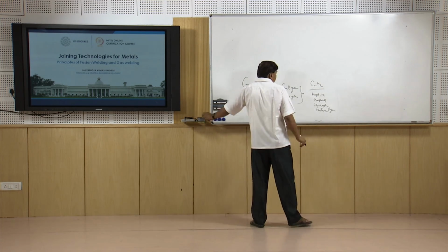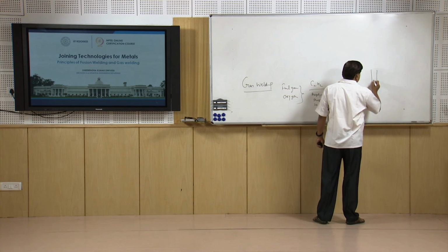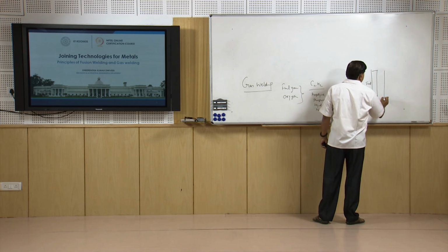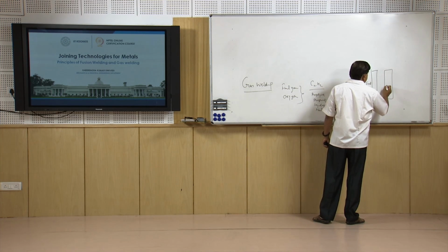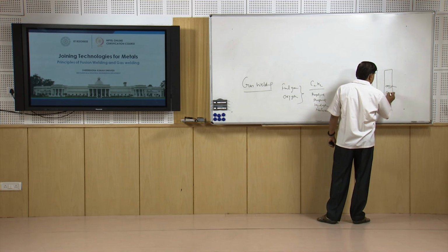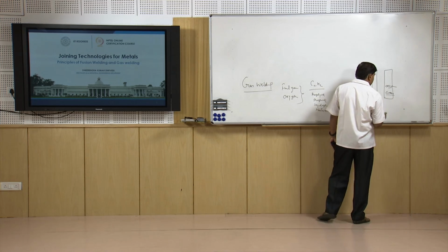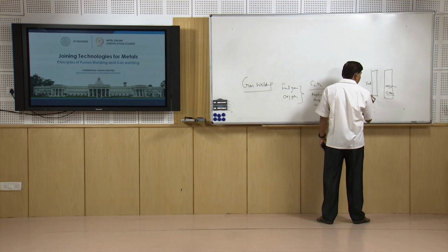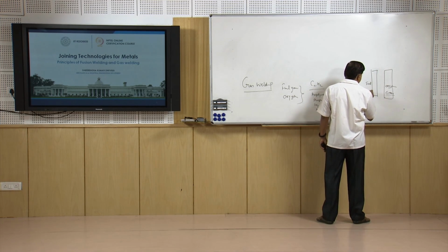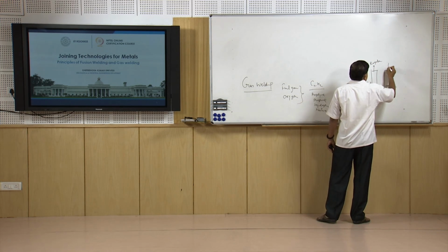Normally, we use one cylinder for the fuel gas and another for the oxygen. The oxygen cylinder is normally coded with the green color, and the fuel gas cylinder with the red color. There is a regulator with both cylinders.